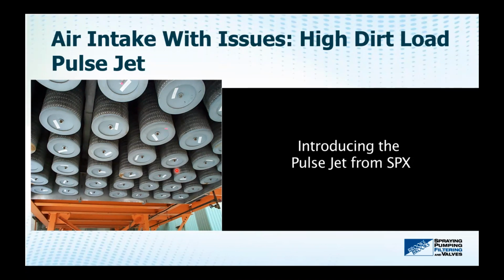When you see the rows of filters hanging down from the housing, there's a controller on the unit, and these are cleaned in sequence. So you might have a row of 6 or 7 of these do that reverse pulse, and then 5 minutes later you might have another row and another row, depending on the dirt load and how it's set up.